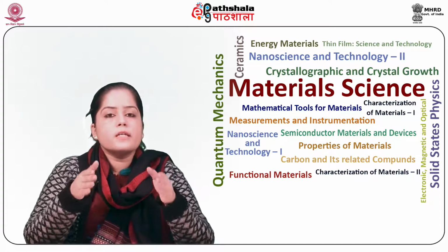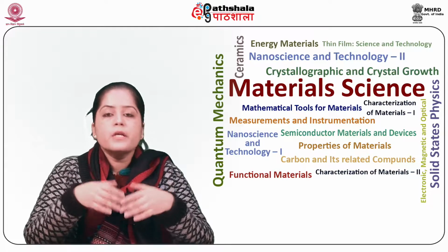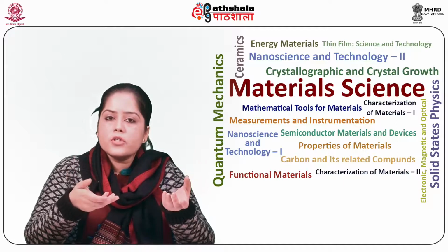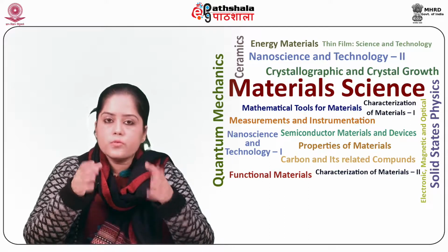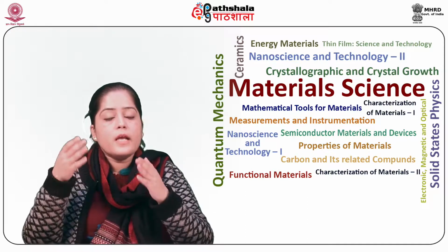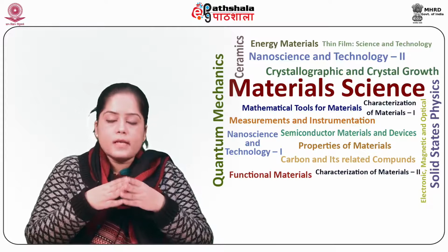This is shown in the figure: silicon nitride, well or active substrate or buried oxide, trench etch, the liner oxidation, fill trench with dielectric, CMP for planarization, trench, pad oxide, substrate, N-well, P-well, and the trench oxide.